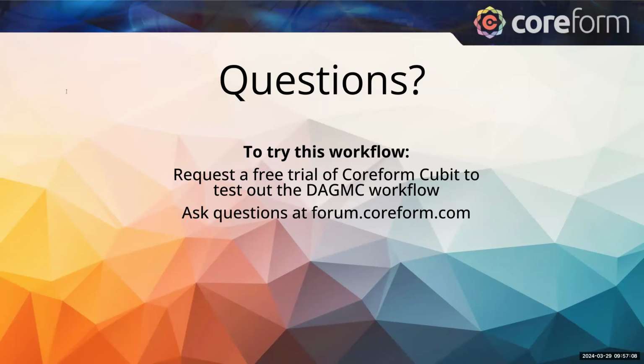And that is true of, in OpenMC, that's true of unstructured mesh as well. So we could generate a TET mesh from this model that we were just looking at in Coreform and export it and then apply that as an unstructured mesh within OpenMC. But we could also do that if the underlying geometry were CSG. So that it's kind of independent from the geometry representation to a large degree.